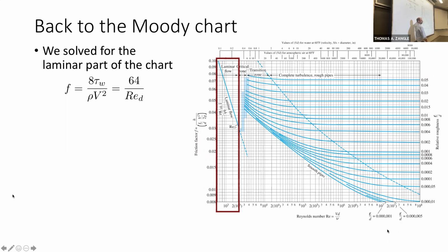And you look up friction factor. Let's say you compute it for laminar flow, 64 over Re. And now you need to know what the head loss due to friction is. You can just rearrange this expression and say that h is equal to f times L over D times V squared over 2g. All right, so that key equation is right here.